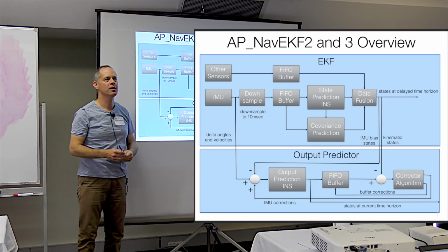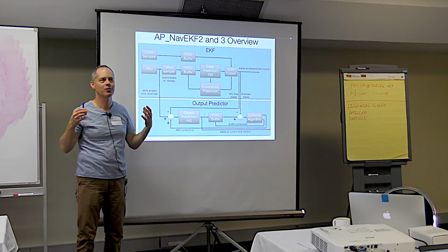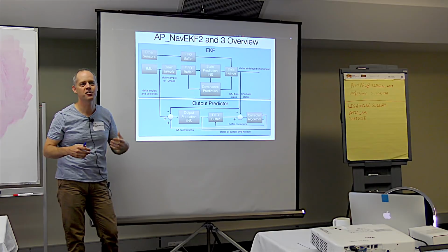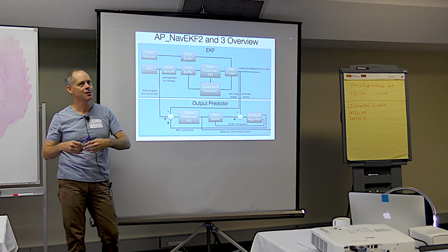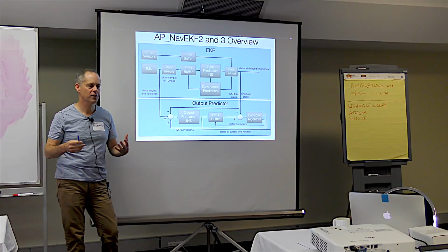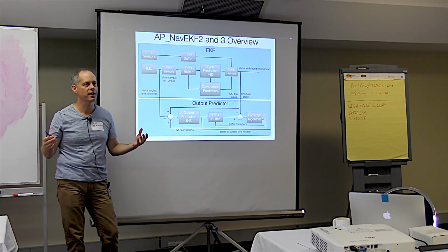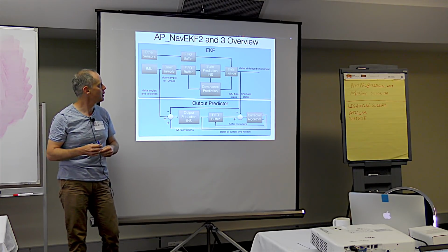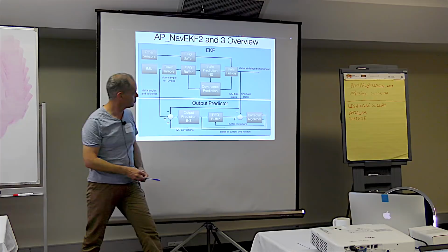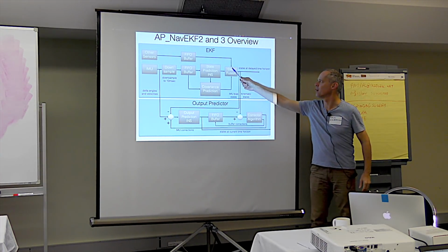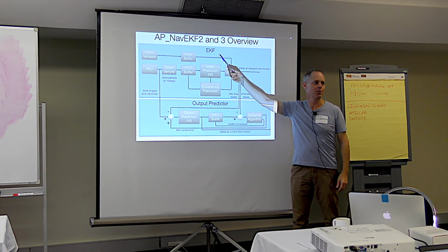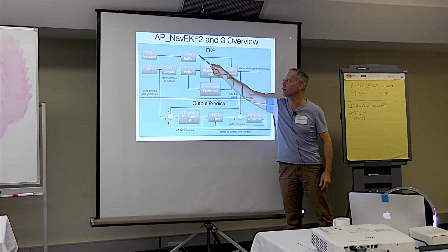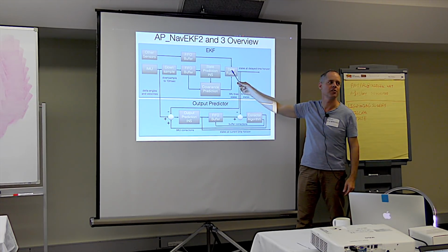And inertial navigation means you do integration. You integrate your gyro data, you integrate your accelerometer data. It's dead reckoning, which means your errors accumulate. If you get large errors, the angle, the velocity, the height, the position, it diverges very quickly, and if the divergence is too great at too fast a rate, then the correction for those errors, which is what happens in this step here, using all that other data, which is hopefully all brought together to be used at the correct point in time, so data needs to be time aligned, that correction is ineffective.